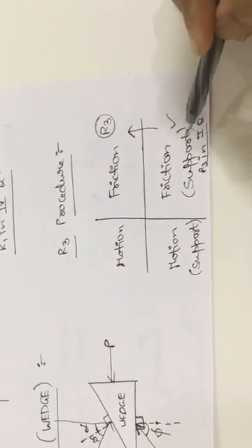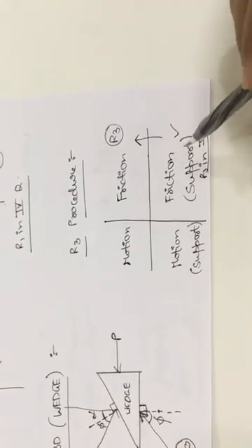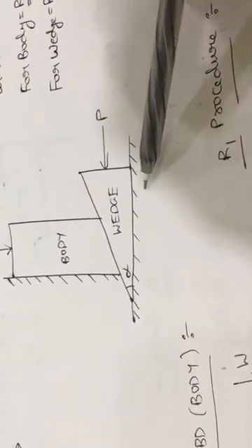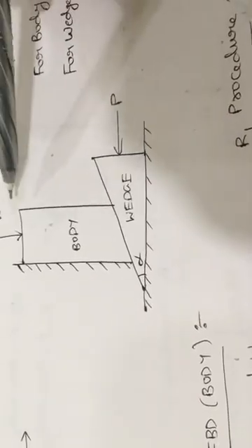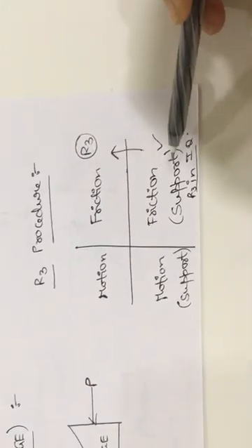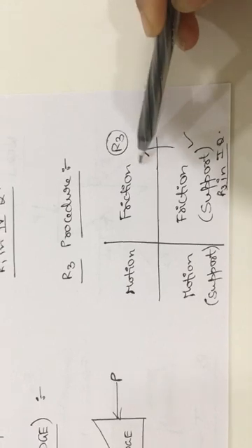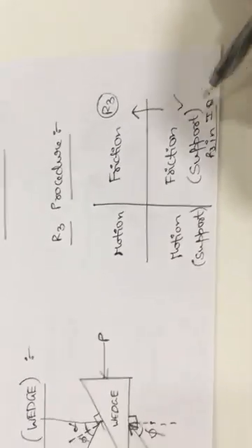Now from this procedure we got the support quadrant exactly. Support is in the fourth quadrant. Now observe the main diagram. From the fourth quadrant, support is acting on the wedge in this direction, which means in the above direction. So in the above direction, from this combination quadrant, you will get the reaction in the first quadrant due to friction. So you will get R3 in the first quadrant.